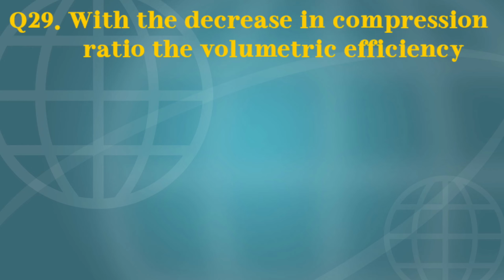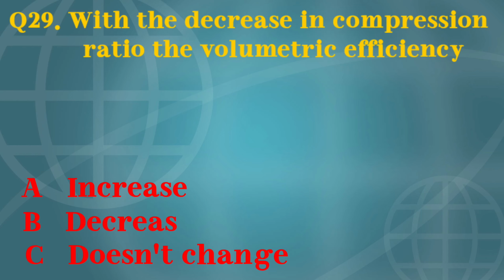Your question is, with the decrease in compression ratio, the volumetric efficiency will be. Your first option is increase, second option is decrease and third option is does not change. Your right answer is increase.